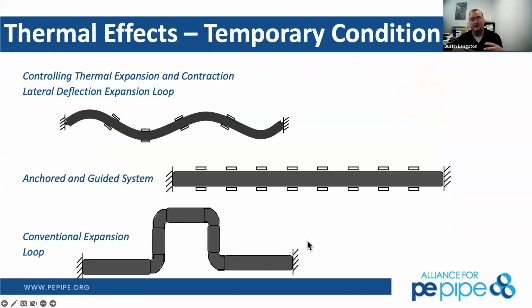And that insert stiffener, you don't need to worry about that as a field guy. All of that comes fully installed and ready to go. All he's doing there is he actually removed the gasket to clean it and put it back on. They come fully built that way, and you just fuse it onto your HDPE pipe on the other end.